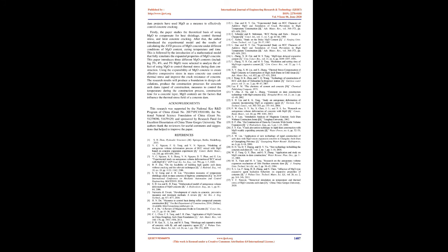This paper introduces three different MgO contents, including 3%, 4%, and 5% MgO, selected to analyze the effect of using MgO to control thermal stress during dam construction. Using the expansibility of MgO concrete to create effective compressive stress in mass concrete can control thermal stress and improve the crack resistance of concrete.